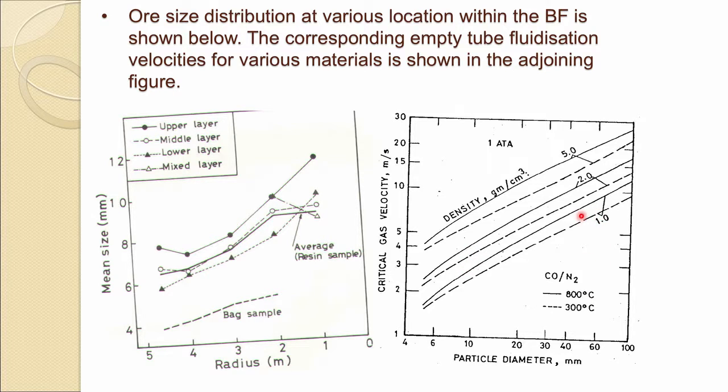And these are also given at two temperatures. As the temperature increases, you can see the fluidization velocity rises, because the gas density becomes lighter. So, you need a higher fluidization velocity to fluidize the same diameter particle than at the lower temperature.